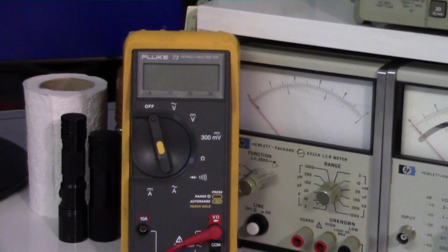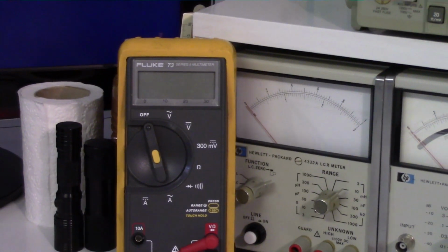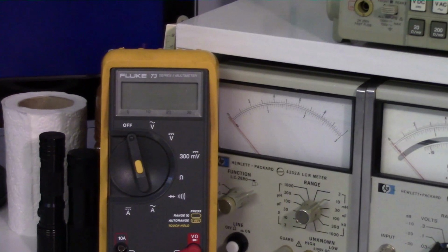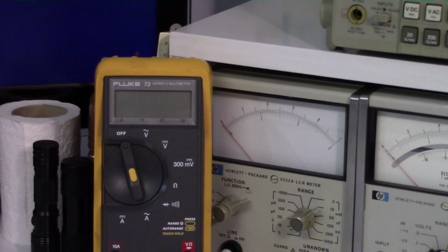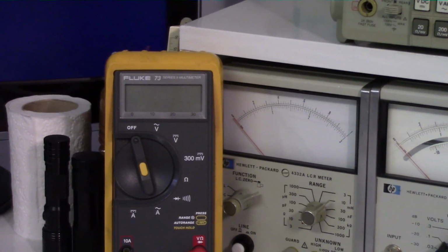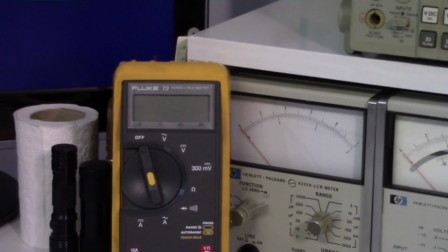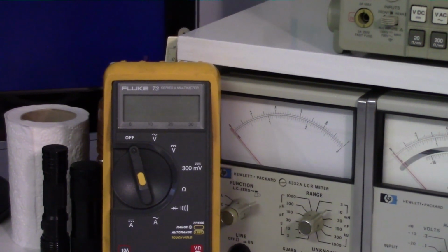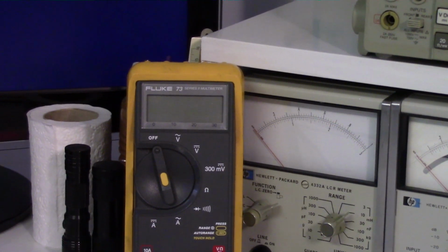But if it doesn't, but it still is a true RMS reading meter, it'd be a pain in the butt to do so, but you still could manually take voltage measurements and convert them over to dB and look for that 3 dB difference. So you're not totally sunk, you'd just be doing a lot more work.